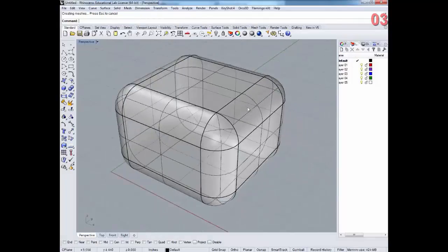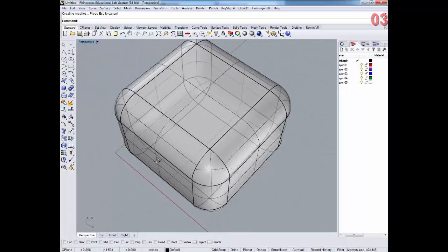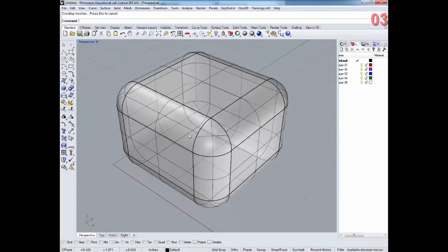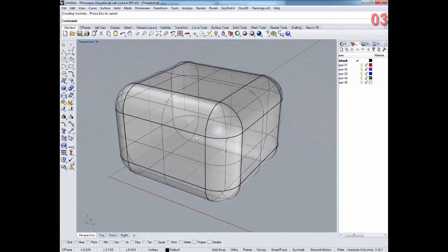When you run a fillet, basically it takes that edge and the radius that you've provided, and it creates a circle that is that radius and runs it along that edge. Where two or more edges intersect, it puts a patch surface in between them. That's what this surface is. This is a patch surface, and this is sort of like a rail surface. Now, it's good to have preview turned on, because if for some reason your object isn't clean like this, you can always make adjustments during the command line.